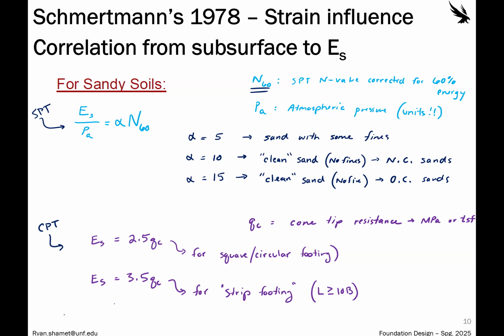And this is what makes empirical testing nice, that these are tests that are performed all the time. Subsurface testing like SPTs and CPTs are performed at any site. So as long as we are matching our empirical relationship to the correct site conditions, then we have a good understanding of some soil properties such as the Young's modulus.